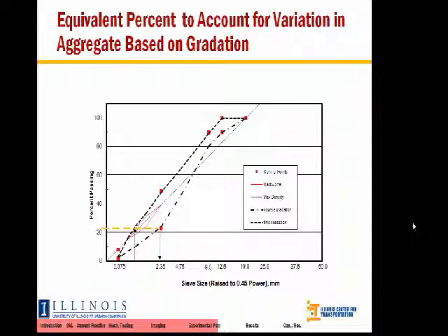After that is done, for the fine gradation, since we know we're working with smaller aggregate in this case, if you do that thresholding for the fine graded mix rather than the coarse, you end up with a smallest remaining aggregate of approximately 0.6 millimeters. Now, to treat all mixes in this study similarly, we need to take that 0.6 on the x-axis, come up and see where it intersects with the fine mix.